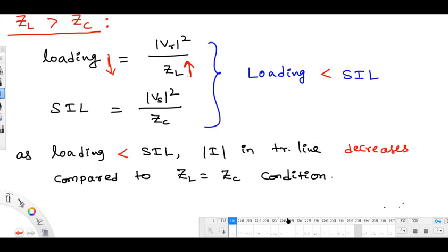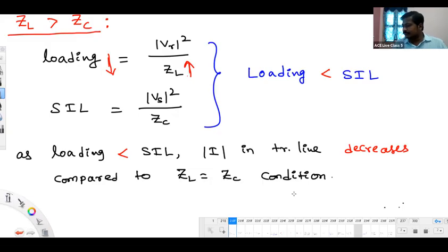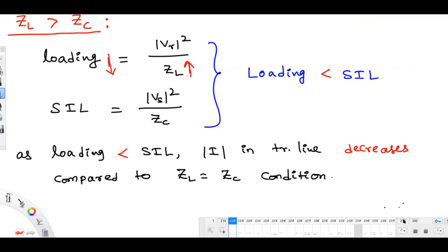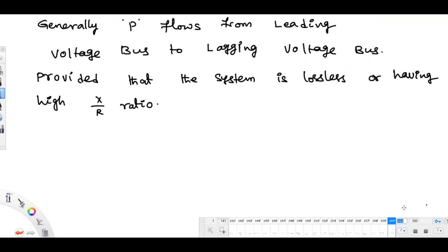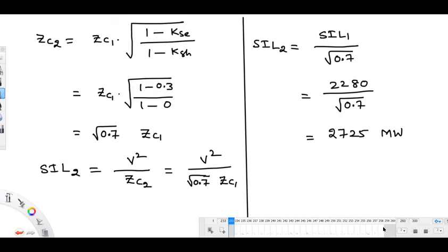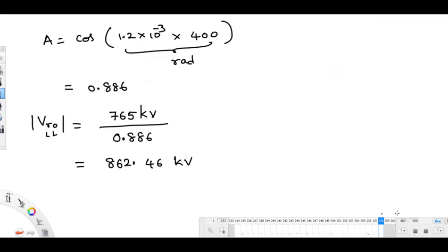Hello, sir. Tell me, Swapnil. Sir, I have one doubt about the bundling of the conductor. Suppose we have bundling of the conductor, and in the single phase line, different currents are flowing. In that case, we have to take the distance raised to the actual current. Suppose in the transmission line, one current I1 divided by 3 is flowing, and in the second, I1 divided by 3. Like this, current is flowing. Then, if we take the distance in the formula for calculation of the inductance, we have to take the power of D as 1 divided by this fraction, sir. Is this correct, sir?